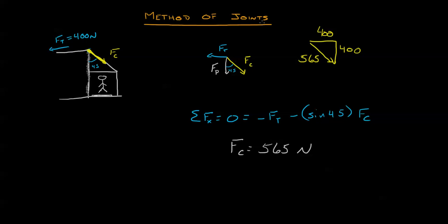The method of joints takes a look at pivot points, joints where members come together. Generally you look at the area where you already have a known, and then you use it to find an unknown. By using this, we can start in one area of a truss and slowly build up to be able to solve all the components of the truss. Now you know enough that if we wanted to, we could use the method of joints to solve for what's happening at this point right here.